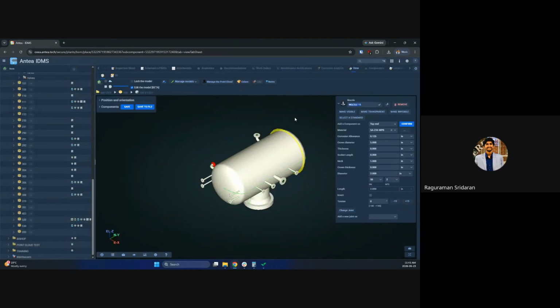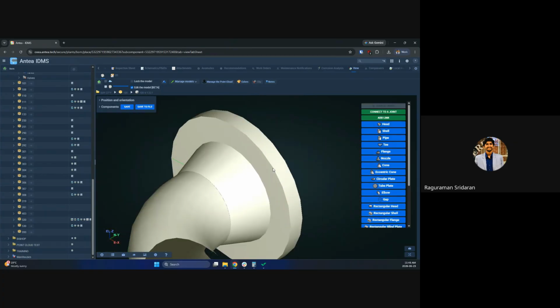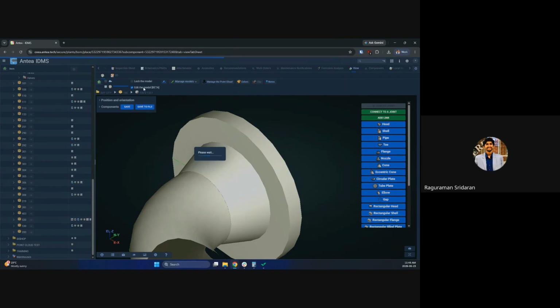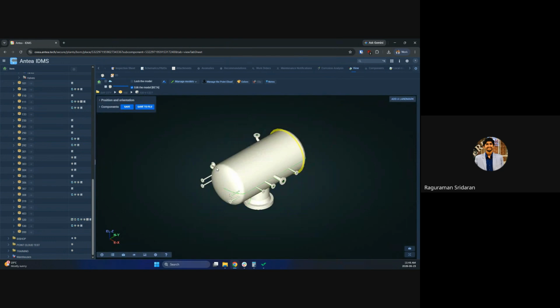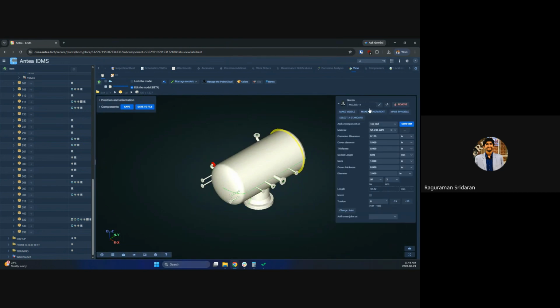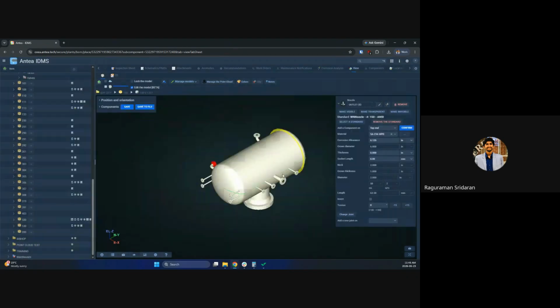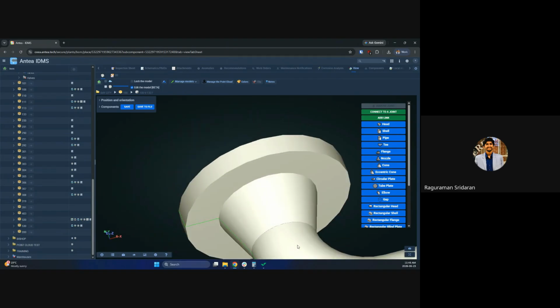And if you see here, if I try to add the outlet with the same name, it won't let me because I just created it. So what I do is come back, disable the edit in the model view, jump back again and try to update that information, and probably remove the orientation of the elbow. Outlet B, and standard has not been chosen. Okay, so we choose the standard. Good.